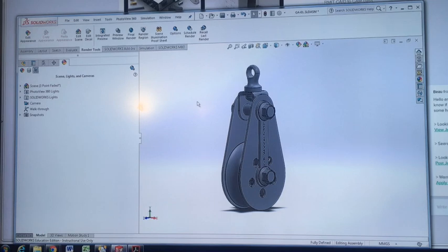The way I typically work, and would suggest you work as well, but develop your own method as you go, I always add materials and appearances first. I play around, get my camera angle right, and then last step, with that camera angle, I rotate the scene or change the environment. What happens with your materials, you add a material, looks good, you get it looking spot on, you change your scene, the material appearance changes. Okay, so there's always a bit of to and fro, but if you keep jumping between the two, it can be difficult to just settle on one or the other. While you're learning, just try and get all your materials right, and then just play around with the scenes to see what works best.